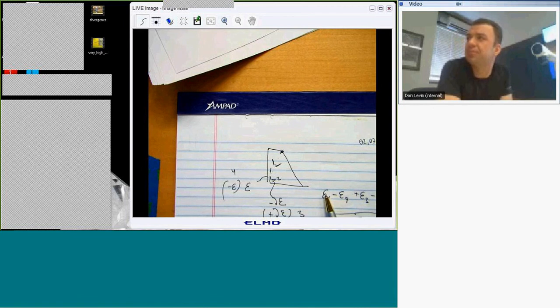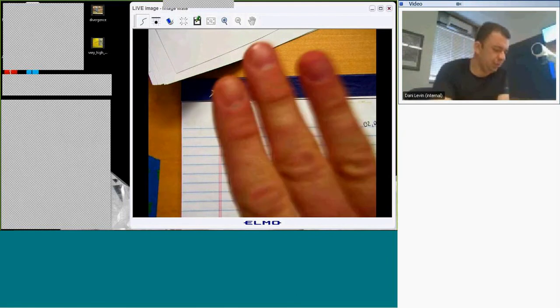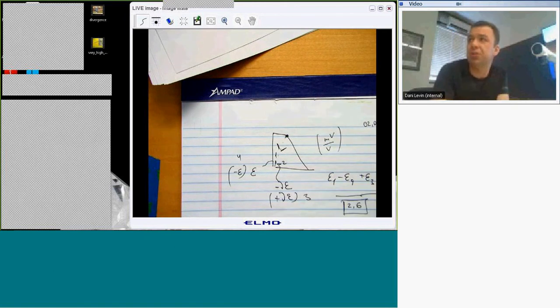Yeah. And how are we able to distinguish between which modes are vibrating with the accelerometer? Okay, so in the way that I set it up in the test, you have two readings from each of the bridges. One reading is your typical called millivolt per volt. This is your reading of this bridge. Okay, the amplitude, and also we have it on the frequency scale. We do a quick FFT of these two signals.